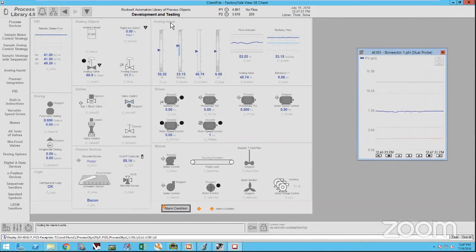And like I said, all the alarming settings are already standard. You can set it by default, and if we're using that Application Code Manager, you can set all of these defaults automatically. So once you set it in Application Code Manager, you hit generate code, and all of that would be defined for you. You don't have to manually go in and do it. So the idea with all of these is that at commissioning, we don't require you to open up Studio 5000. The goal is for you not to have to do that. You should be able to do every configuration change that you need to from the HMI. Now, if you're still trigger happy like me, there's no reason why you can't open up Studio 5000.